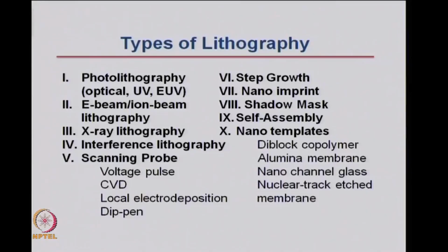So, different types of lithographies exist which are important for different sizes of the patterns or the thicknesses of the patterns which you are going to imprint in your device, and this will restrict the ultimate size of your device. There are a large number of types of lithography, and each type has its advantages and its disadvantages, and of course, the primary thing is to get the pattern of your choice.